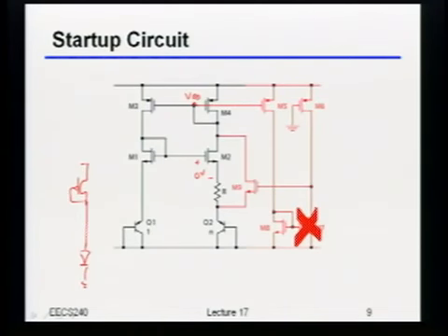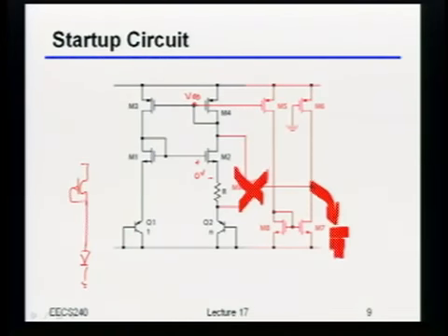Well, okay. Once current starts flowing through here, now actually there will be some real current flowing through there. I'll mirror that current over to here, and as long as I've set this circuit up with the right ratios, meaning that this current, once the circuit is running, is always way bigger than that current, that will shove this back down to ground. This will shut off. I'll shut the switch off, and the whole circuit just sits the way it was supposed to sit. Okay?